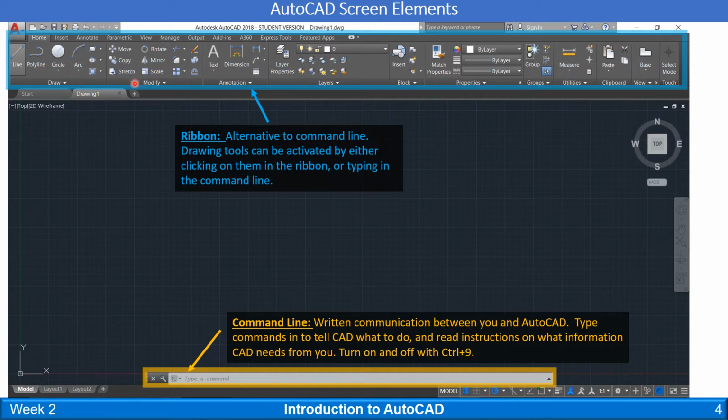Here's the modify tools. So if you want to move something around or copy something, mirror it. Annotation, so this is where you're going to add dimensioning and text. We'll do more of this when we get into the layouts. Layers, this is a great way to organize your work. Over here, when you're defining line types, always keep this set to defining it by layer, and we'll go through how to organize your work with that. Groups, utilities. This kind of goes in order. The most used tools are over here on the left-hand side, and it's just like reading left to right.